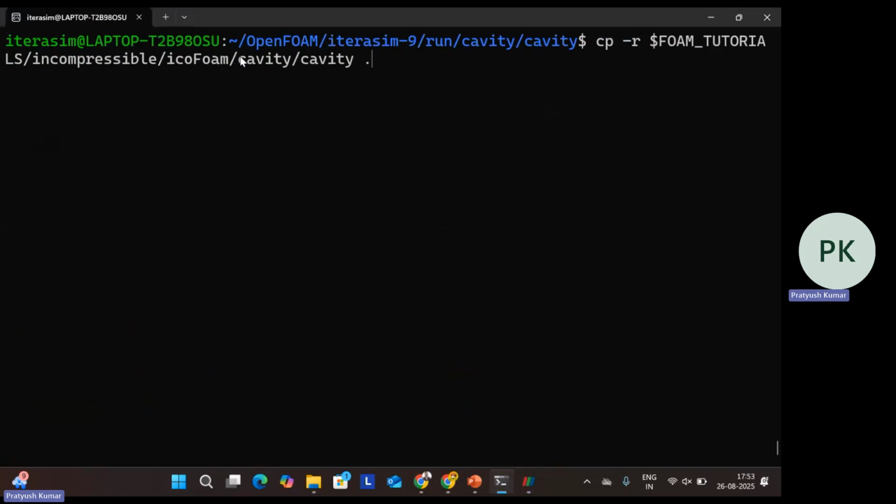That doesn't work for me. Maybe you have not created your run. Is it because of this OpenFOAM 9? Yeah, you have to create it. So if you type run, it is saying that create one folder with the name of the Rajesh 9. Then inside that you create the run. Okay. So in OpenFOAM I have to create this folder. Then after that you create.